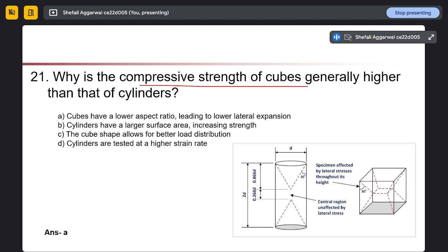Next question is, for a given workability, the water demand is reduced. So it will result in higher strength, decrease in cement content, lower strength, or foam in concrete mixing. This is a statement given in the slide itself. Imagine we have fixed a workability at 75 to 80 from the slump test, and we are reducing the water demand.